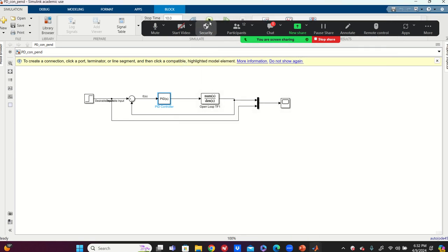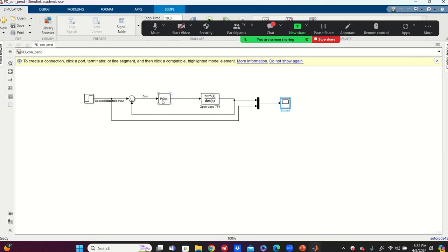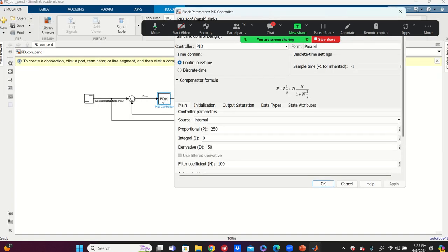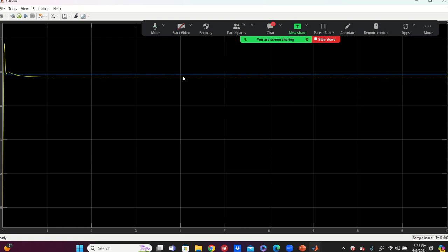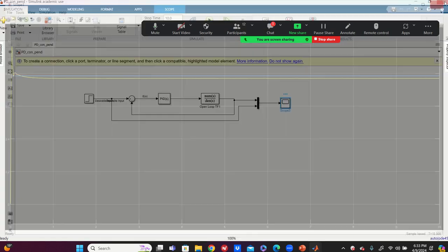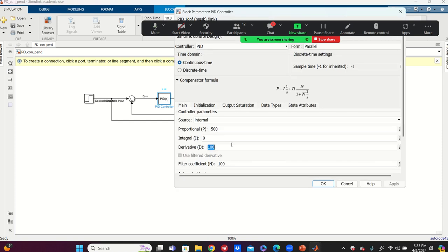See? Here we go. We are getting close. And now what I'm going to do is make this 500 and 100. Here we go. We are getting very close. But you have to fix this again. So you need more damping here because you have a little overshoot. We don't like that. Okay? So this is you. Based on experience, you have to do that. For example, I can do it